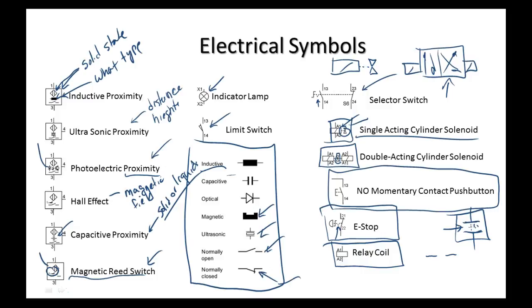Okay, if you go out and buy one, do you have to specify you want one for solid? No. Usually they give you a dielectric constant range, so you would have to know what range it covers. It's going to see multiple things. So as far as I know, you can't have a capacitive sensor that senses nothing but glass, unless you had the ability to set an upper and a lower limit.